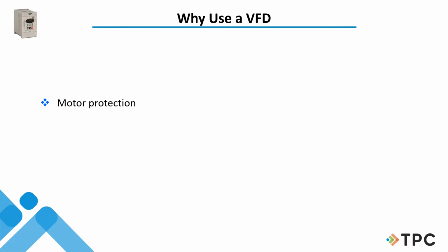But with a VFD, if I want to, I can say, hey, when I reach a certain amount of torque, I'm just going to shut down. So I could be protecting my equipment or whatever I'm moving on that equipment. And I don't have to wait until it gets way overloaded to shut this unit down. I can do it on torque. So again, it's in the parameters, you have to set it, but it's another way to protect some of my equipment.